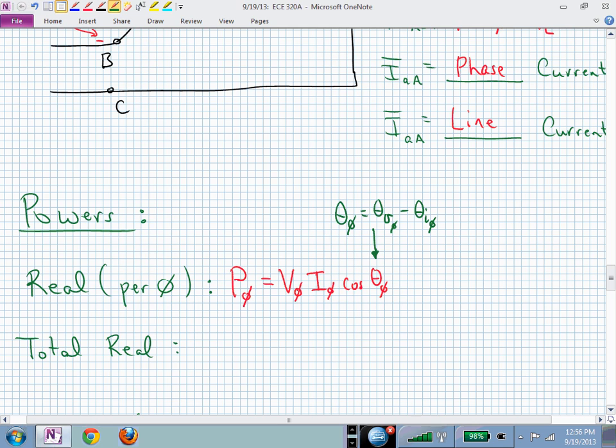Is that okay? Now, that buddy of yours just went out and measured the line voltage, didn't he? And maybe he gave you the line current. Can you use either of those two directly in this formula? For the Y configuration, which is which? Or which one can you use? The line current. That's the same as the phase current, isn't it? So you know I sub phi.